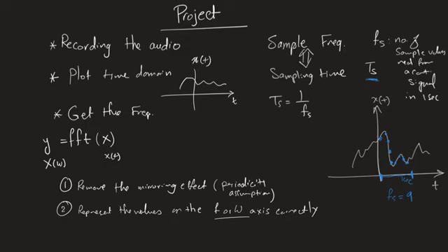The reason for those comes from the fact that when you deal with a discrete situation, there is an inherent assumption, because that's what happens when your time domain signal is discrete, that in the frequency domain the signal will become periodic. And again, when we deal with the frequency domain representation of any time domain signal, we cannot deal with the continuous.